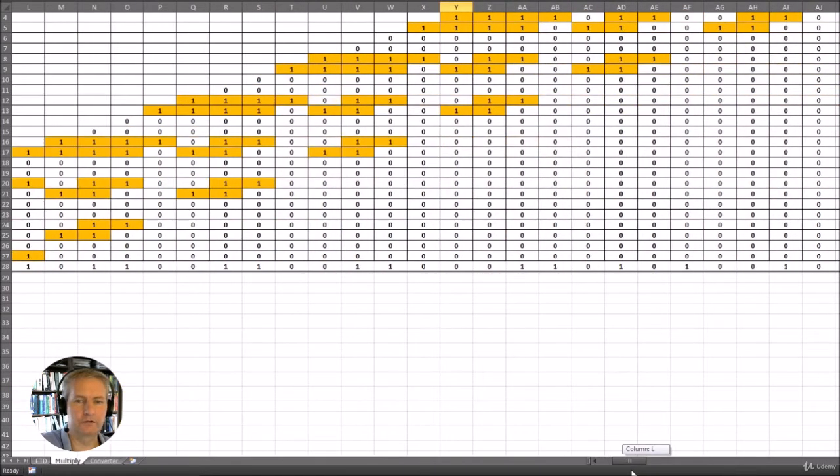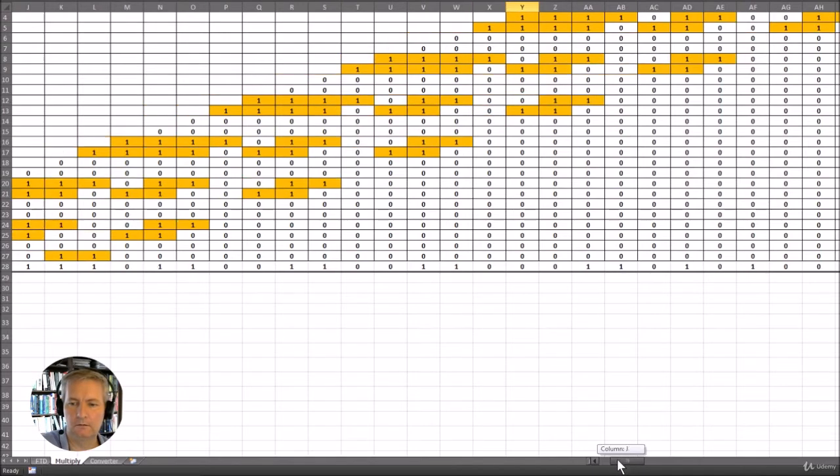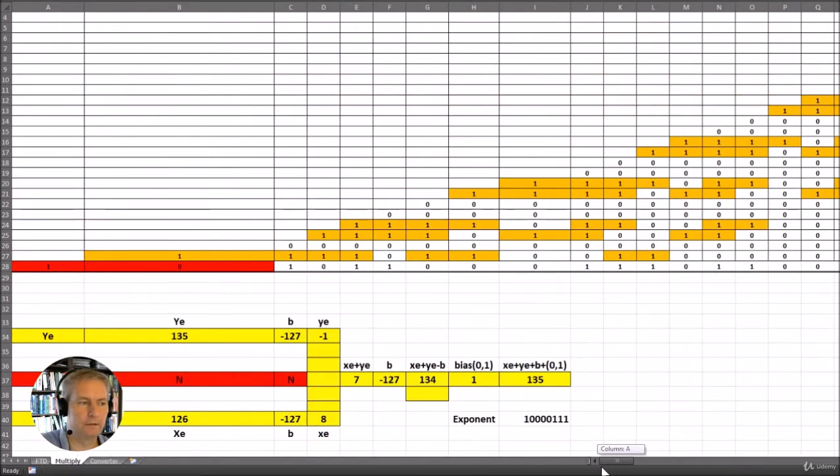And what I've done is I've just highlighted the values of the 1 just to see the changes that map through whenever you change the value of the decimal input. So we have our 48-bit number here, and you'll note that I've put the first 2 bits in red because these are the first 2 bits that are going to be left of the decimal point. So in effect the decimal point is going to be at this point here.